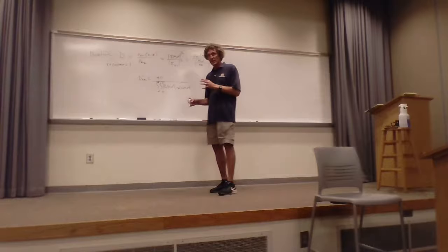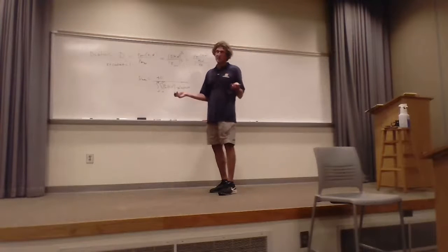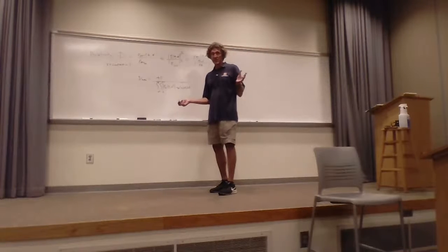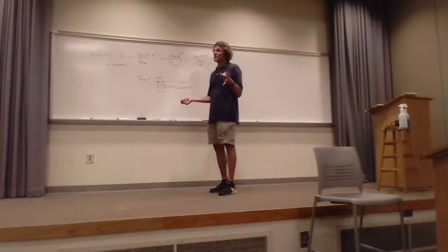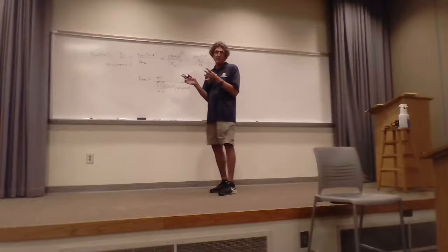I'm not done, because here's where it gets good. So big deal, it's D max. What good is it? Well, first, the higher that value, the higher the focusing ability of the antenna. So the better off you are focusing energy at a certain power in a certain point in space, all right?